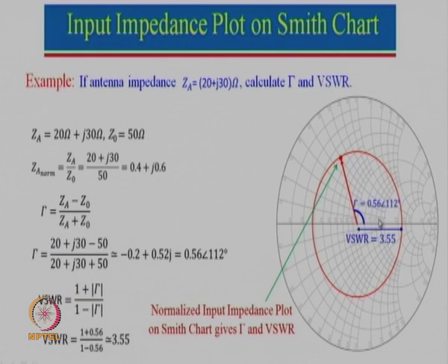You can see here there is this central line, which is actually a real axis line. Impedance here is 0 and it goes to infinity, and generally the Smith chart is used for normalized impedance. Whatever the characteristic impedance is, in this case 50 ohm, we normalize the value with respect to 50 ohm. So, you can see that Z normalized is given by this here.